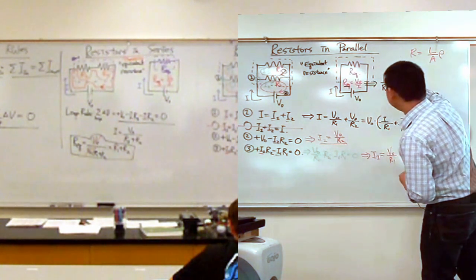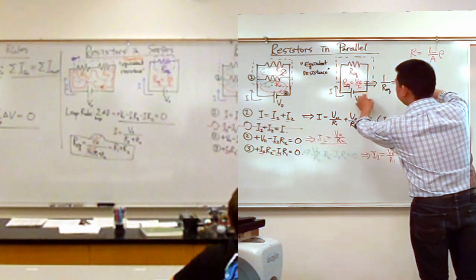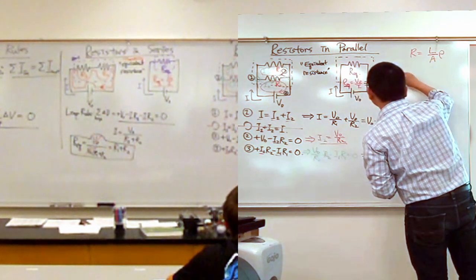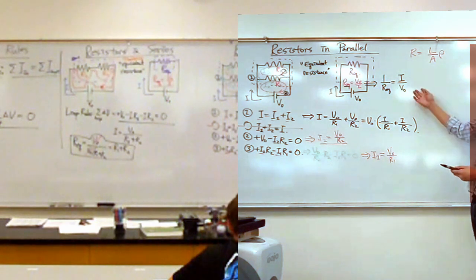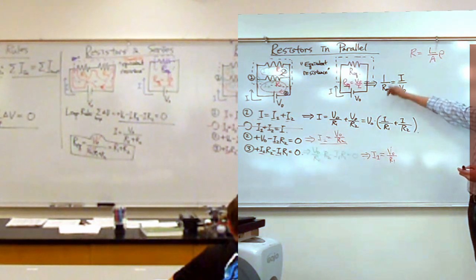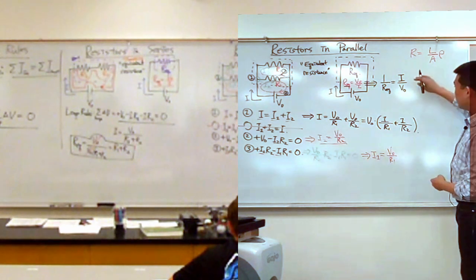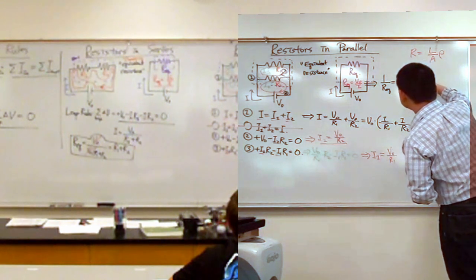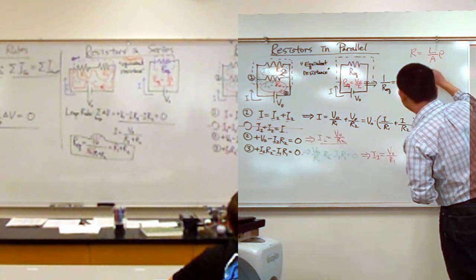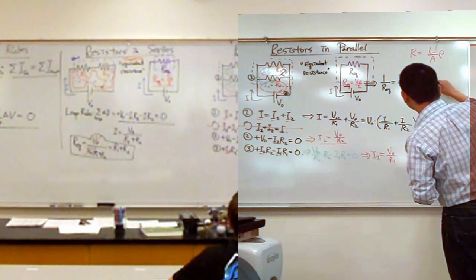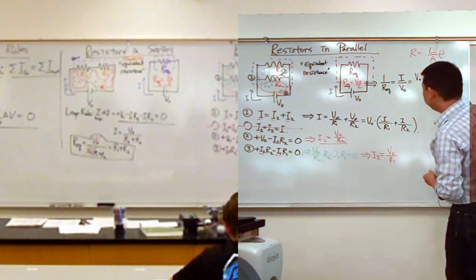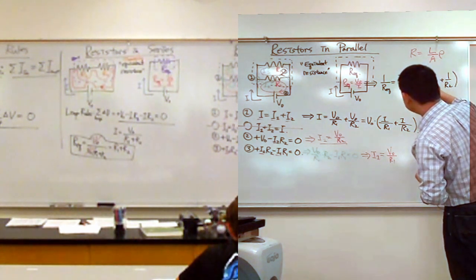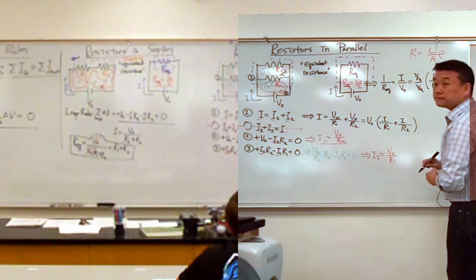Okay, so if I'm doing that, then what I'm writing down here is I over V0. This makes it simpler because I'm going to avoid the nested fractions this way. So I is just V naught times 1 over R1 plus 1 over R2, divided by V naught. So V naughts cancel.